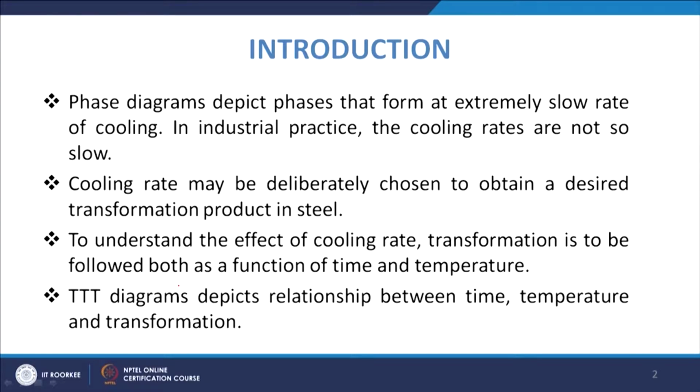What we need to understand is that when we are cooling, there are two things. One is time: with time how the transformation proceeds, as well as at what temperature. So, we come to one temperature, and at that temperature with time what will be the transformation, how the phase will be transformed. For that, in this lecture we are going to discuss the TTT diagram, which depicts the relationship between time, temperature and transformation.